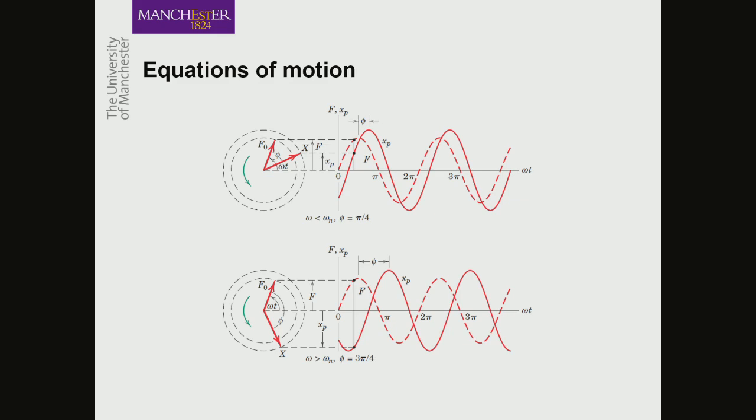So we apply the force, and due to the dampers, the mass will still follow, but it will lag a bit behind. So this is what happens here, okay? You apply the force, the displacement increases, but comes a bit late due to the damping of the system. The difference between the applied force and the displacement, how much it lags, is called the phase angle.